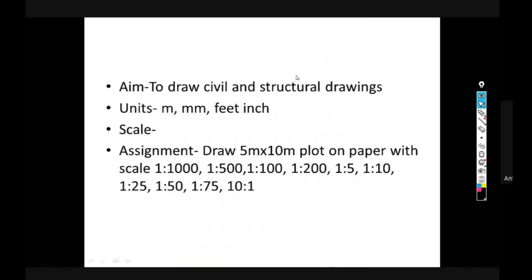First point is always, when I say 1:100, this is site, this is paper, right? Now when I say 10:1, same. One is site, 10 is paper.